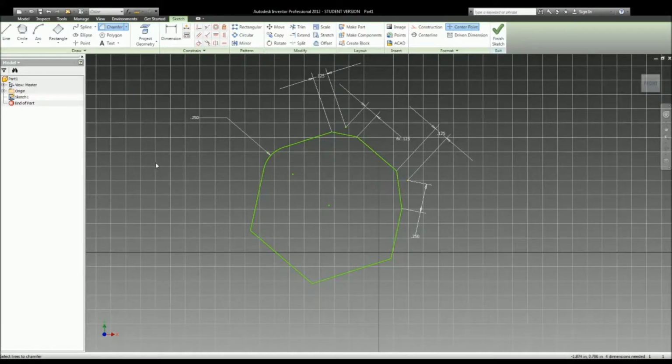Now if we go to this one, the last option is chamfering based on an angle, okay? So distance and angle. I'm just going to go ahead and do this so it's a little bit easier to see instead of me trying to explain this in a terrible way. First click, second click. The first click is where the cut-in is. The second click on the second line is how far from that point, and then how far from the point that it goes back, the angle based on the corner. Okay, so the angle here is 45 degrees to this line.